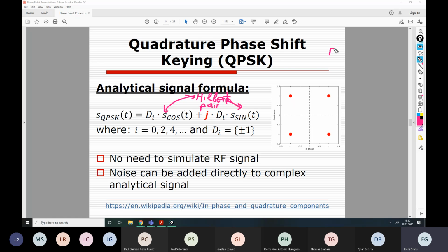So what does that mean? That means that instead of adding noise to this modulated signal, we can add noise directly to +1 or -1. Just one number can be noised, and then we can compare it with the threshold. Effectively, that would give the same result. If you actually try that for binary phase shift keying with signal to noise ratio calculation by standard deviation, as we have done in our practical exercise and course project calculations, then you would see that it would give the very same BER value. Of course, accordingly, you would need to calculate the new signal energy, which is 1 in our case. So that's working, right?